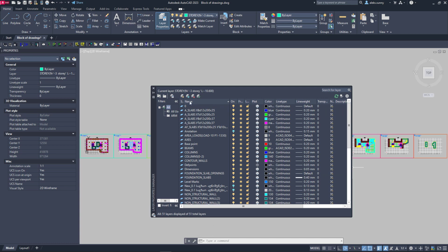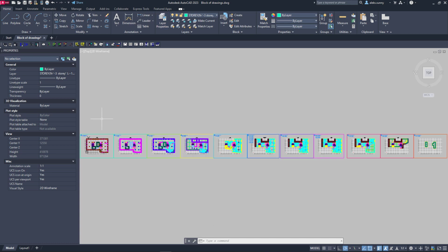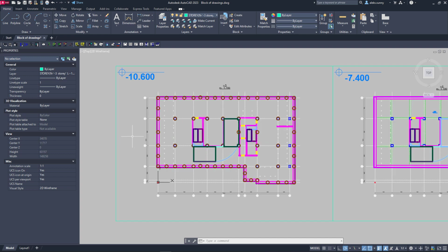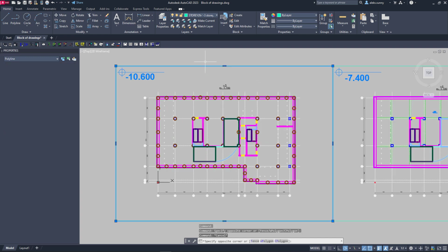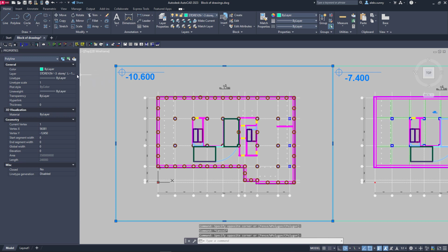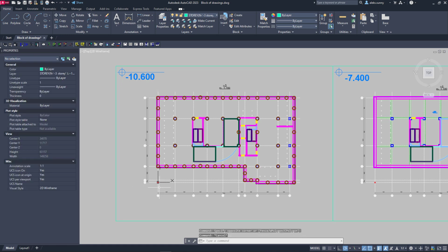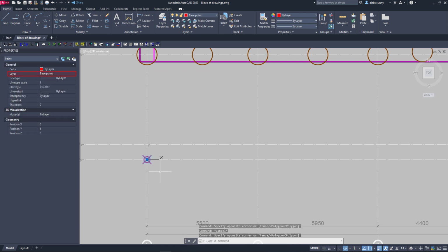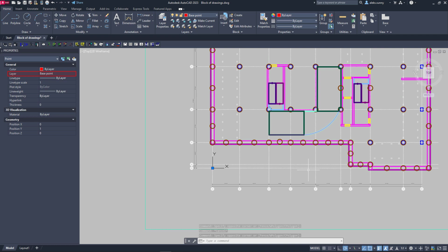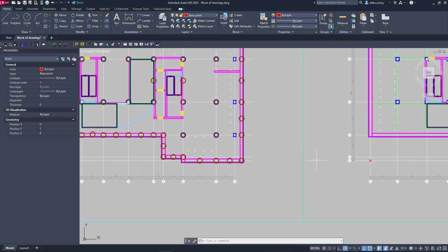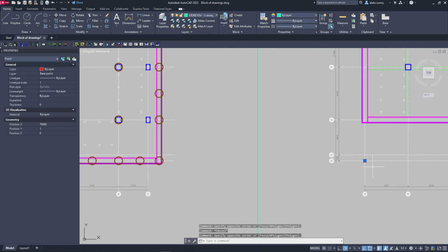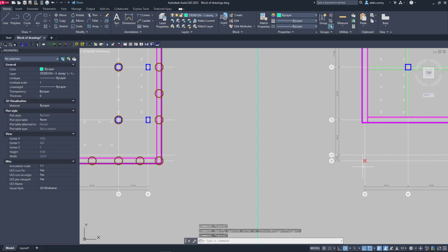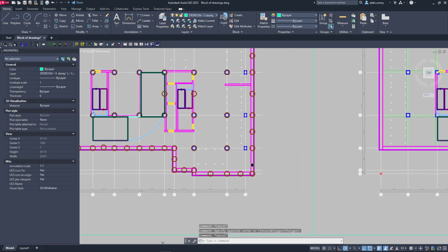In such a drawing, it is necessary to place floor plans inside frames, and for this frame, indicate the name of the story and its elevation. The base point that is located on each floor plan allows you to correctly align these plans in a vertical direction. This base point will be placed in the 000 coordinate of the story in LIRA-CAD system.